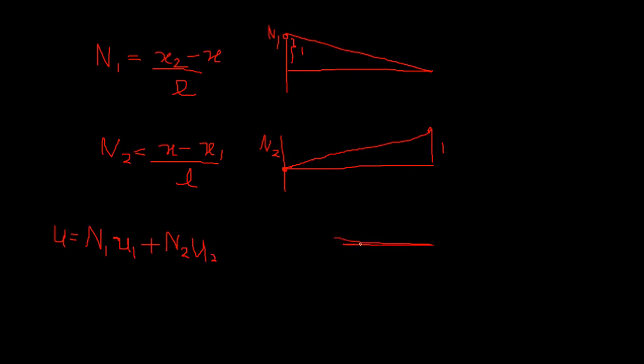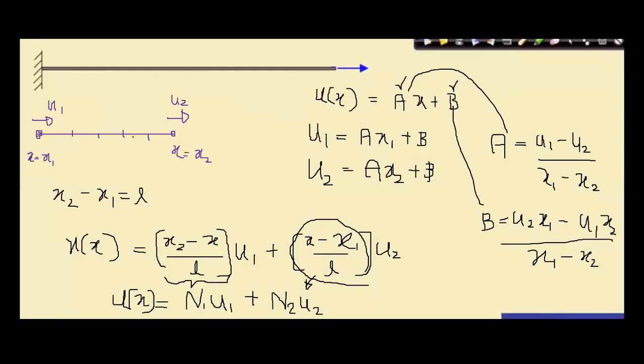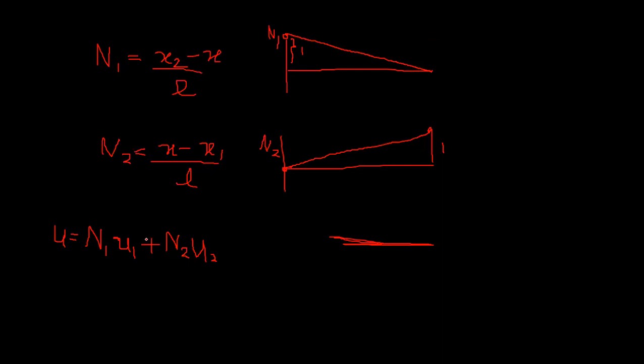So let's check. This element is a rigid body moving in the x direction. If it is a rigid body moving, you know u1 is equal to u2, and whatever displacement, it's like a car moving on a highway, right? If the headlight moves 1 meter in the direction, the tail light also moves one meter, and the person sitting in the driving seat or any other point will move exactly 1 meter. So u1 equals u2, and any displacement at any point becomes u, right?